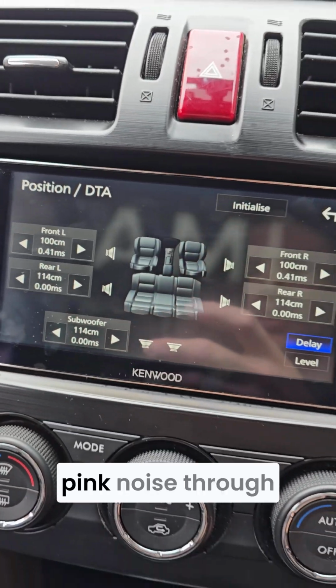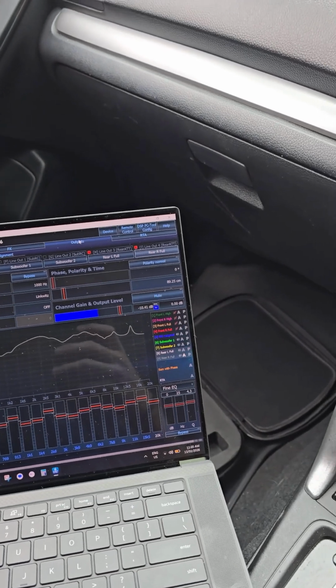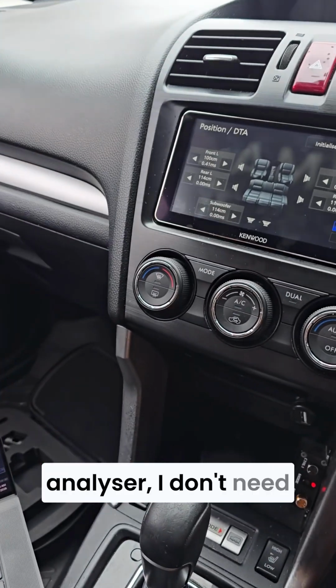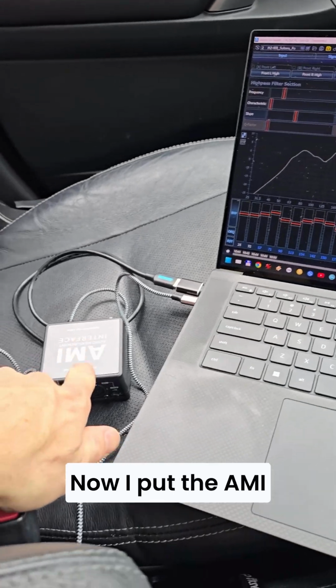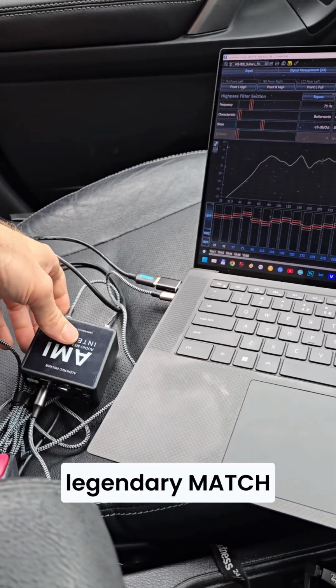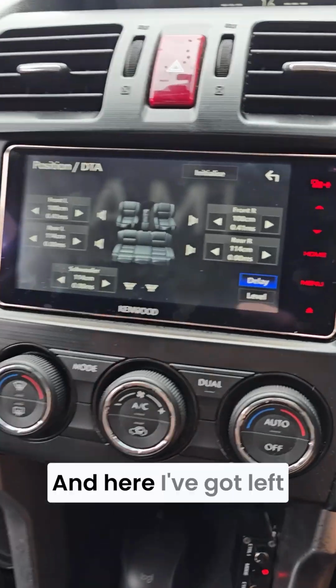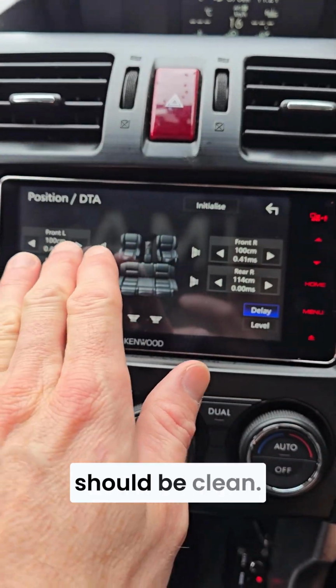I'm playing back pink noise through the Kenwood deck. Here I can just turn the speakers on, but for the input analyzer, I don't need the speakers actually playing, so I've got them all on mute. Now I put the AMI connected to the DSP that I've got installed, the legendary Match 5.4 DSP, and here I've got left and right channel at the same distance, so now the signal should be clean.